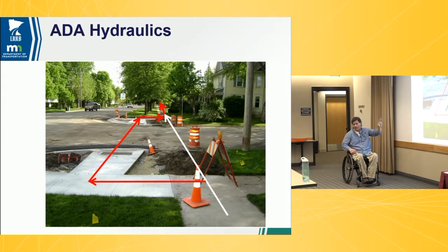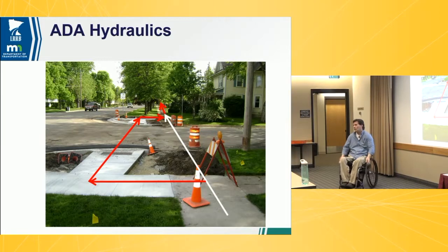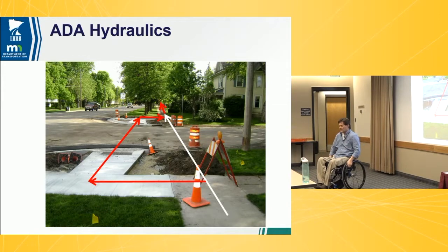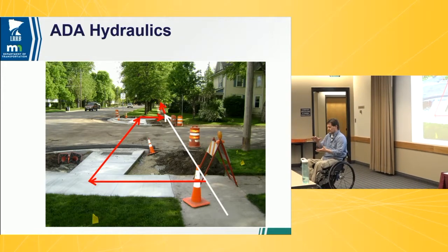But we were trying to avoid those catch basins. So now we're basically saying if those catch basins are in the way, part of the cost of doing business, move them out of the way. And we're trying to be selective how we do this. We're actually turning that existing structure into an ADA safe grate, 1/2 inch opening or less.